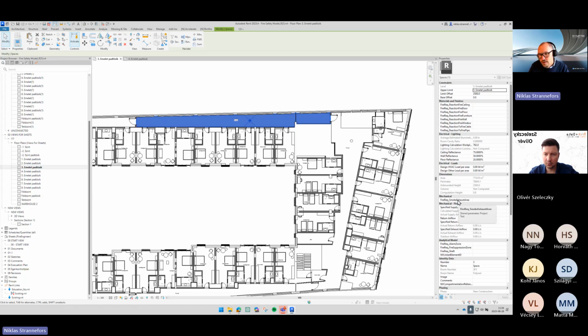And of course, why showcase this from the beginning, we can check what area these are, because we have perimeter area here. I know everyone does it a little bit differently, but Revit will always check the interior area, meaning the inside of the room, space, volume.